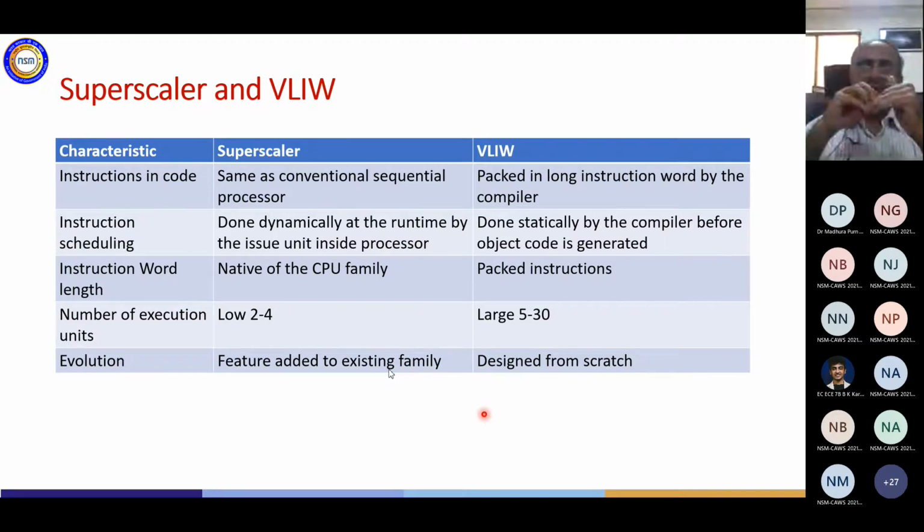If the access is faster, it is wasting cycles because the data has come but the instruction is not coming. However, as you are mentioning, if it is slower, then there is a penalty. When the actual instruction has come for execution but the data is not ready, that particular execution unit will be stalled, and that will reflect in real time loss of performance.